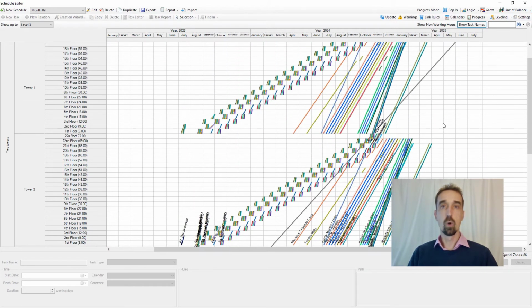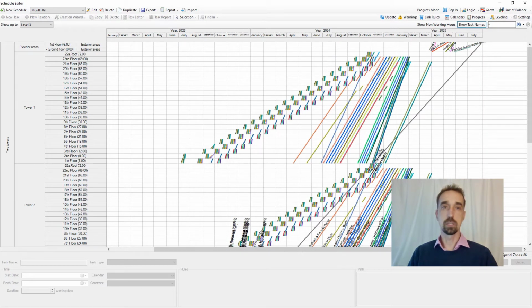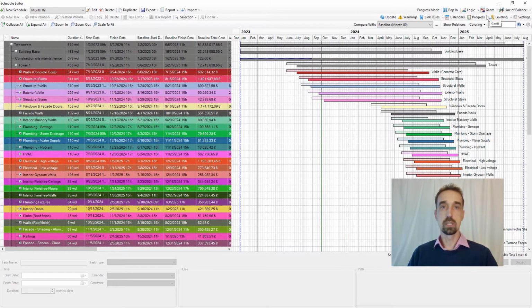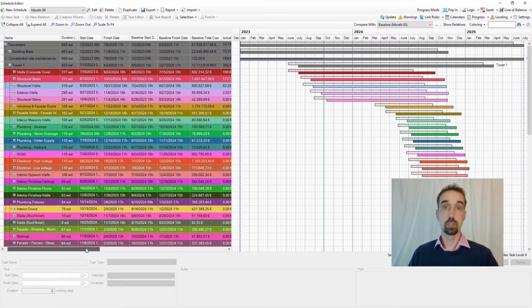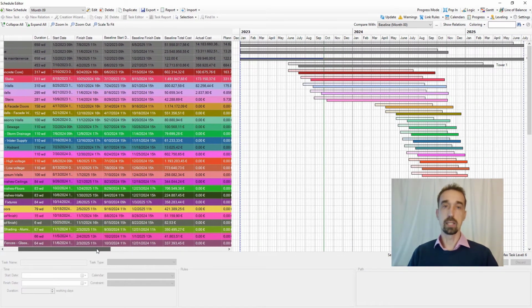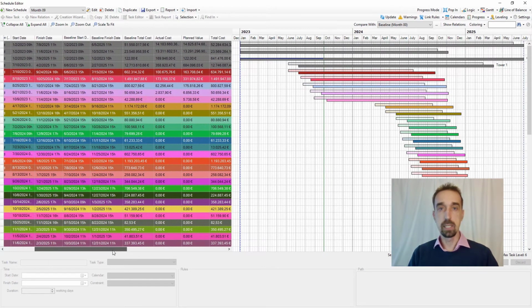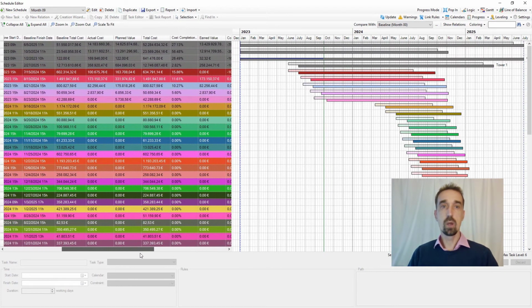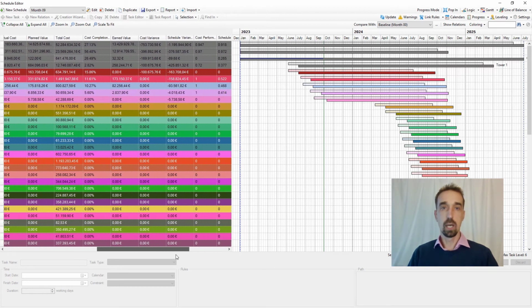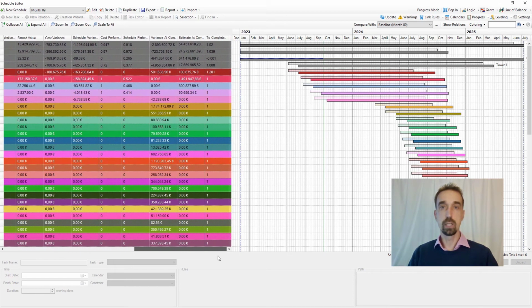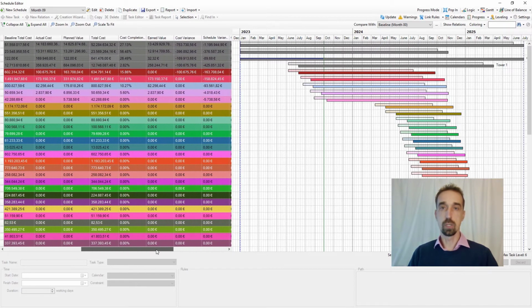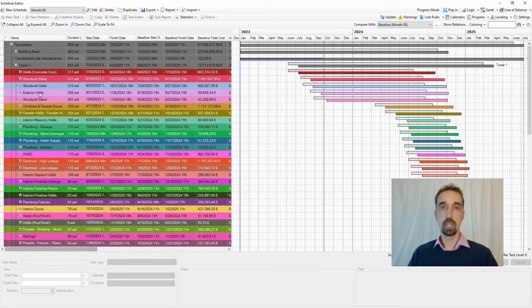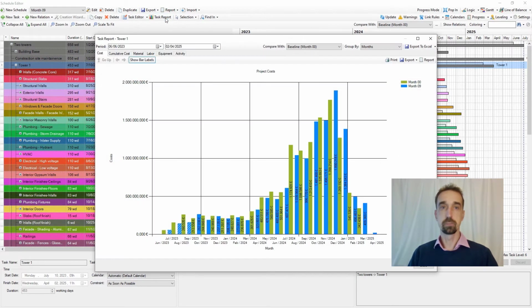But more importantly, all key performance indicators such as baseline and actual cost, cost variance, earned value, cost and schedule performance index, which give us real information about the project performing against the budget and how close this project is to being completed compared to the schedule. All these KPIs can be found as information instantly updated for each task after each progress entry. This way, participants on the project can analyze all relevant information directly in the BEXEL Manager.